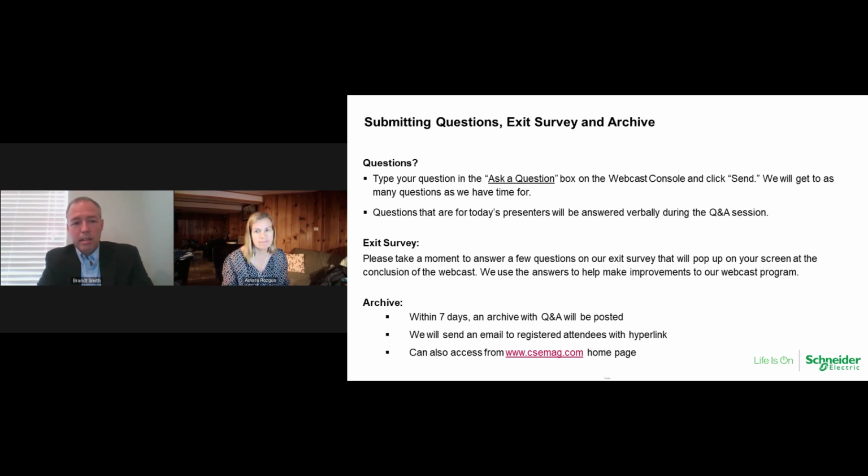And actually, the gas insulated switchgear, especially at 35 kV, typically costs less. Even at 27 kV, it's very attractive. Most people's 27 kV switchgear is based on 35 kV class switchgear. So the cost itself for the equipment, it's a better cost. There's other advantages of it as well, beyond the safety, the reliability, and the footprint.